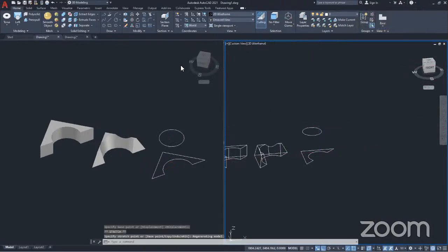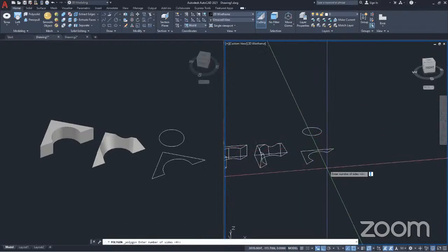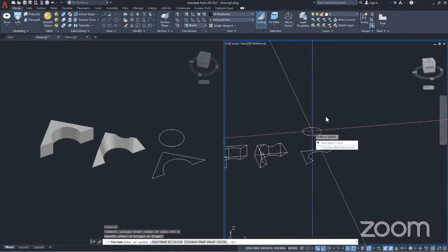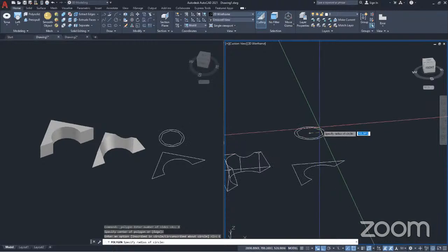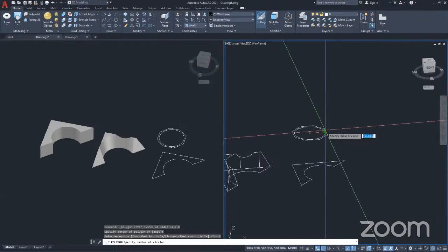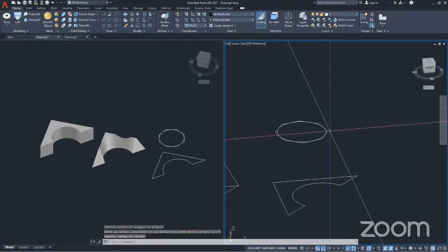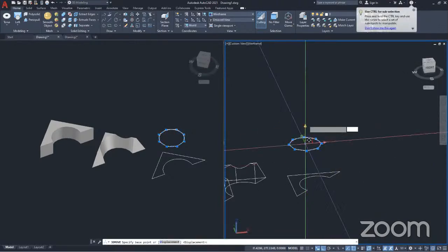And then on top of this circle, I'll create something else, a polygon. Let's see. Number of sides. I need the number of sides to be 8. Octagon, yeah. And circumscribe. We can just go like so up to this point. And then I'll move it upwards again. Move. We move upwards.